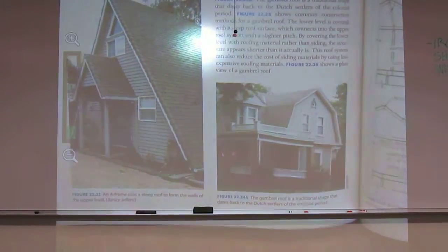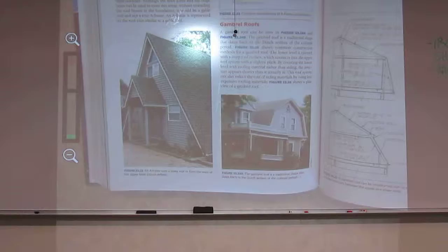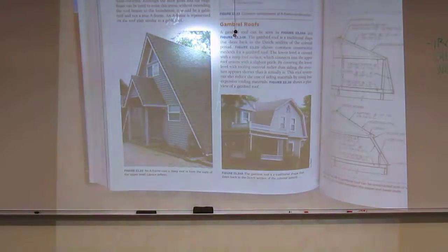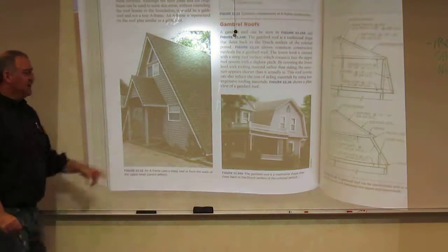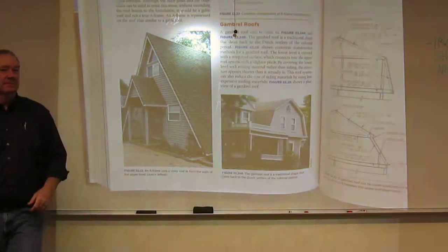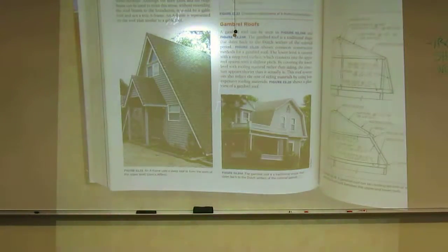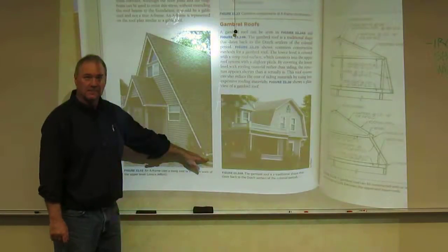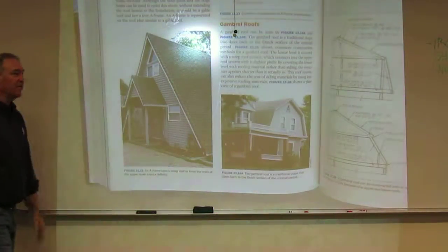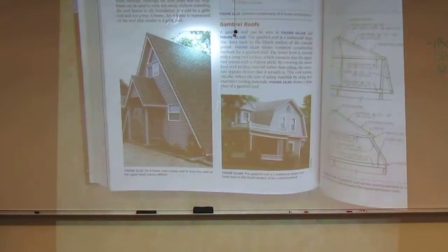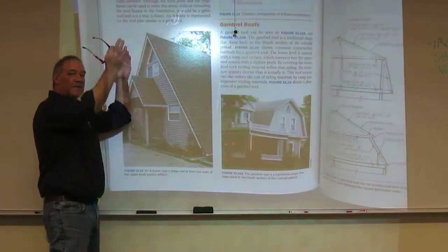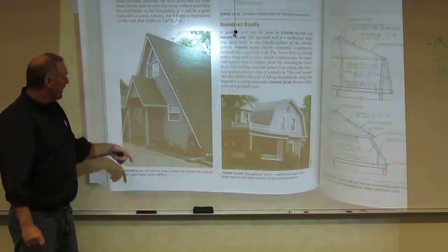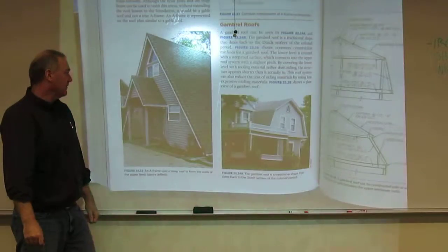All right, so that's a gable. Next one's an A-frame. We've all seen these. We kind of depict them as cabins in the mountains. An A-frame, what is it? It's a wall that's been tilted to form a roof. That's in essence an A-frame. This is built like a wall, usually goes clear to the ground, and is tilted over to join at the middle. This is not a truss system. In essence, many times there's not even a beam. They're just held together by their own weight. Real good roof when we've got very extreme climates, especially a lot of snow.